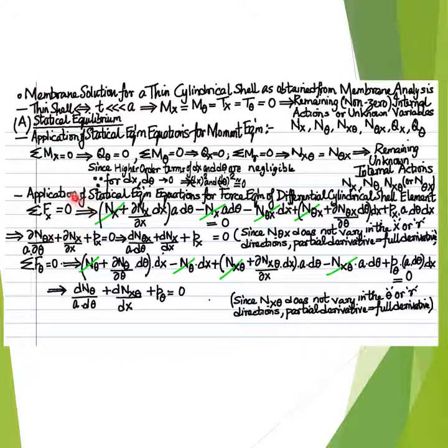Considering the force equilibrium of the thin differential cylindrical shell element illustrated in the previous slide in the coordinate direction x of the selected cylindrical coordinate system, one can write the statical force equilibrium equation in the coordinate direction x as represented by this equation here.